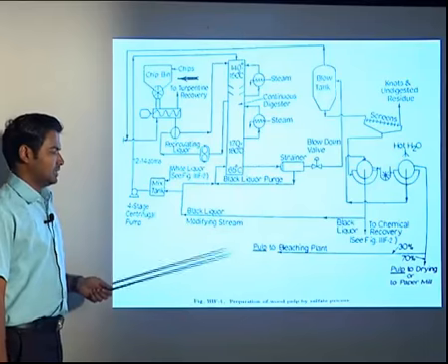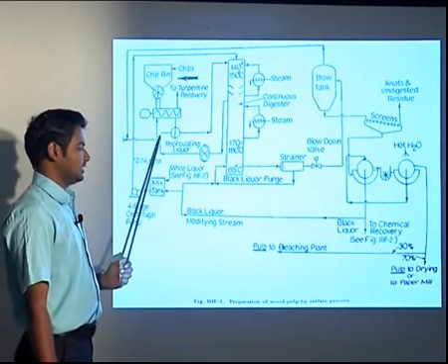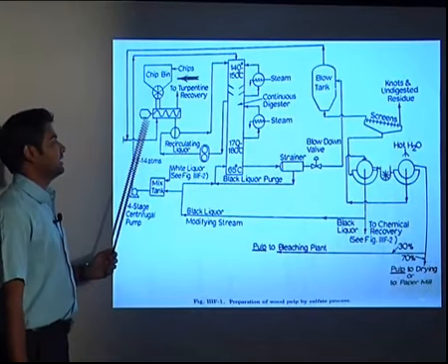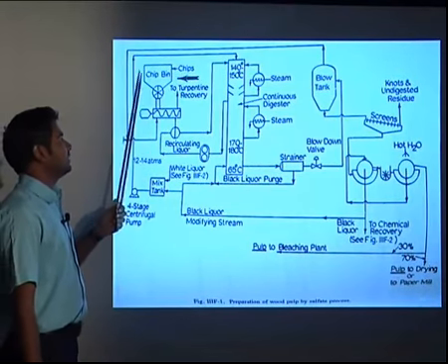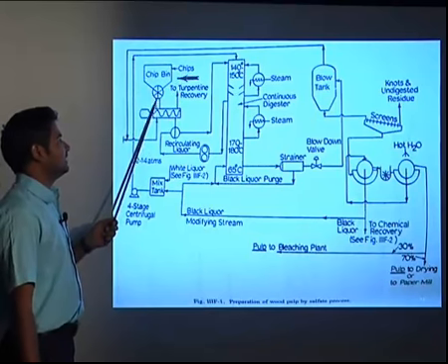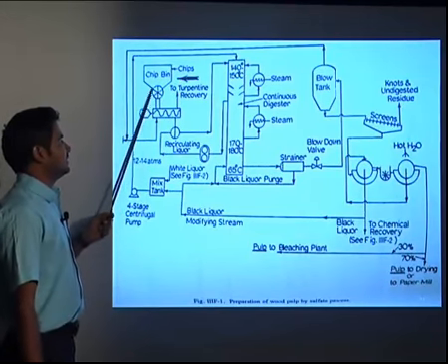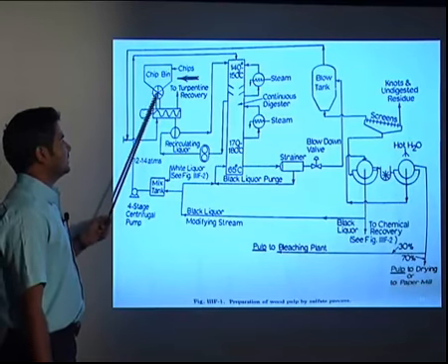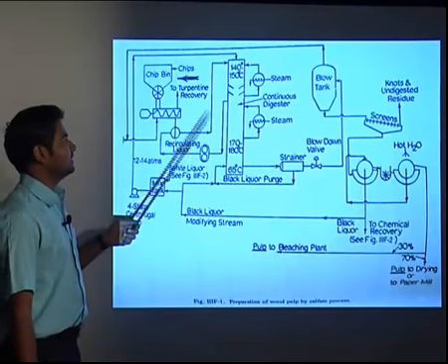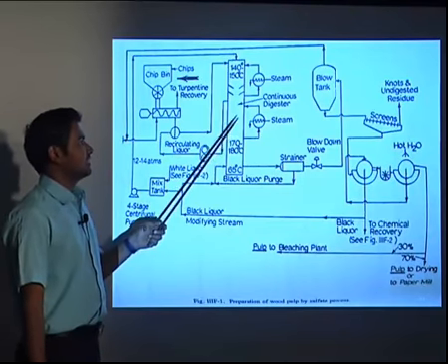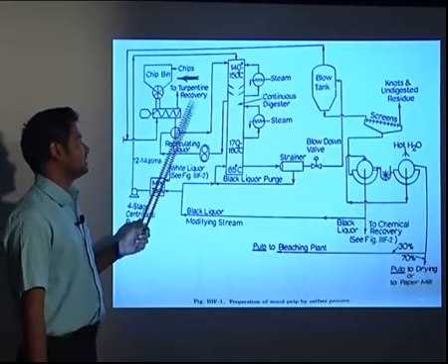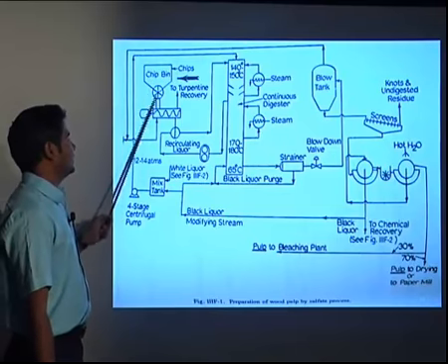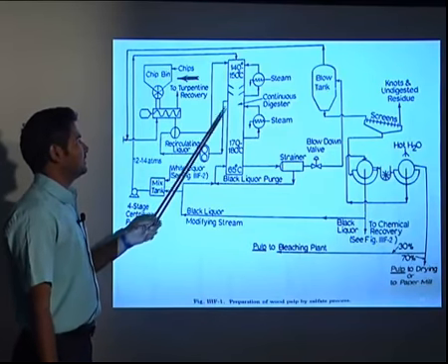So this is the first step where we have to prepare the wood pulp by the sulfate process. The wood pulp will be shredded finely. Here are the chips, they will come here and be shredded finely, and then they will come into a continuous blender. Here the shredded particles will come into the reactor, the digester, where we are mixing the chemicals. The shredded wood material will come into the digester.